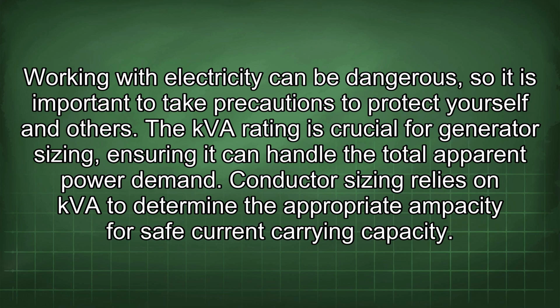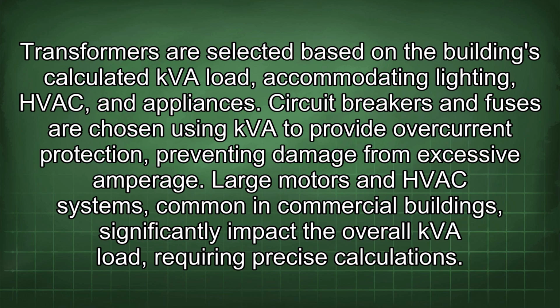Conductor sizing relies on kVA to determine the appropriate ampacity for safe current carrying capacity. Transformers are selected based on the building's calculated kVA load, accommodating lighting, HVAC, and appliances. Circuit breakers and fuses are chosen using kVA to provide overcurrent protection, preventing damage from excessive amperage.